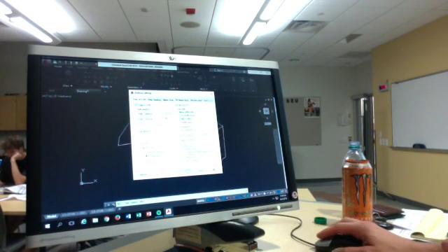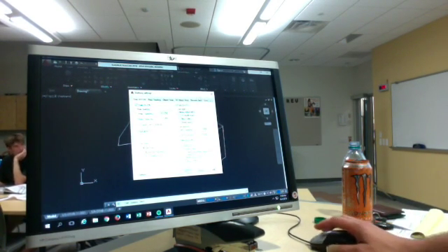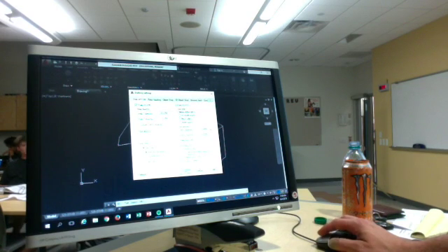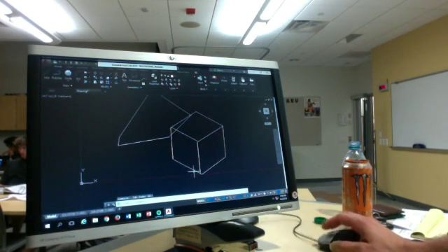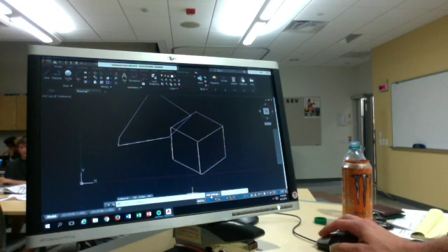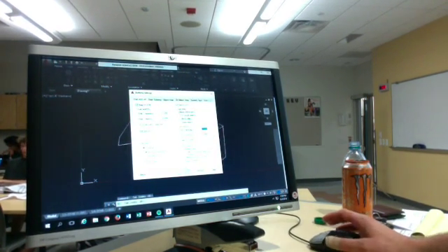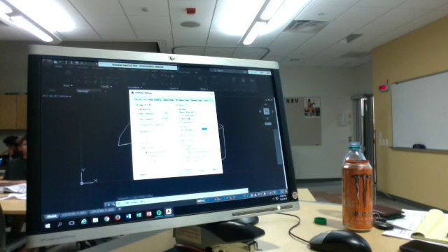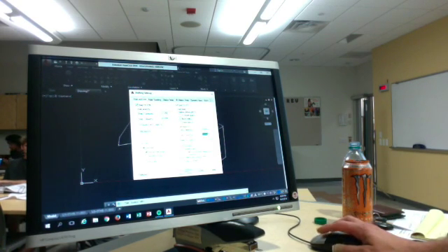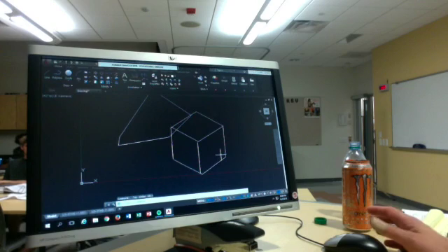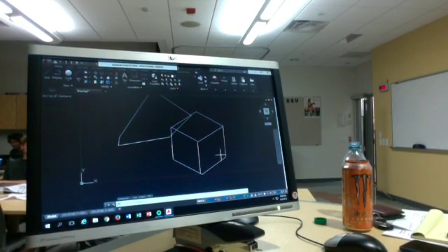So go back to your grid settings. You can change it back to rectangular snap. Grid is on. Grid display type. The important thing here is the grid spacing. Right now, just to show you, our grid spacing is set at a half a unit. You can actually change that. So if you're super zoomed out, maybe you want it set at 5 units. Hit OK. The size of it changes. Typically, you want your grid spacing to be smaller than your snap spacing.